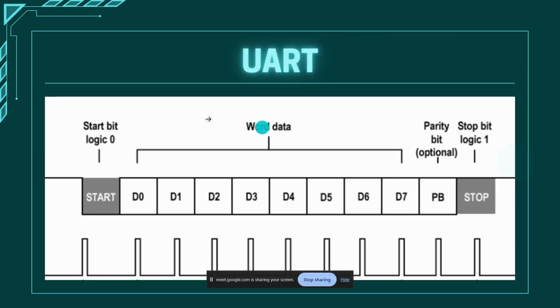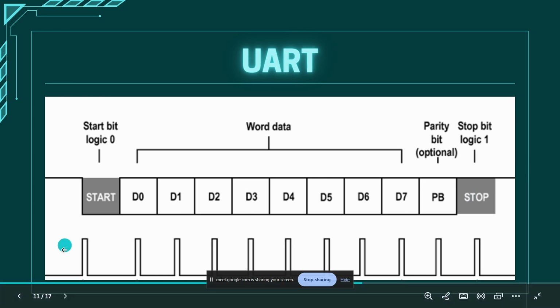So how would that look? This is how it should look. Your first transmitter will be like, oh, I'm starting, and it will send 7 bits or 8 bits of data, and it will stop. And because your receiver is also trying to read the data at the same frequency, it will at least read every bit once.